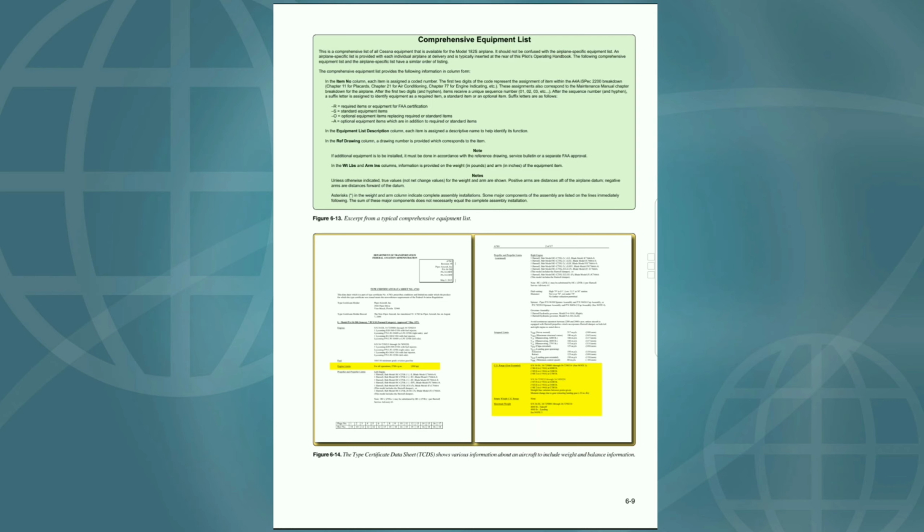S/N 34-7250215 through 34-7450220. Plus 87.9 to plus 94.6 at 4,200 pounds. Plus 82.0 to plus 94.6 at 3,400 pounds. Plus 80.7 to plus 94.6 at 2,780 pounds. Straight line variation between points given. Moment change due to gear retracting landing gear, minus 32 inch-pounds.